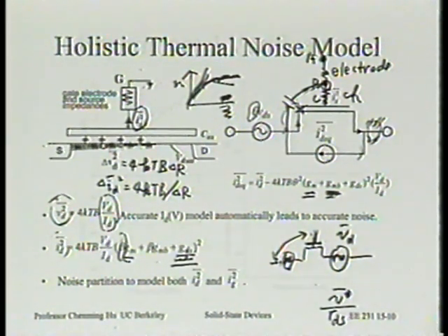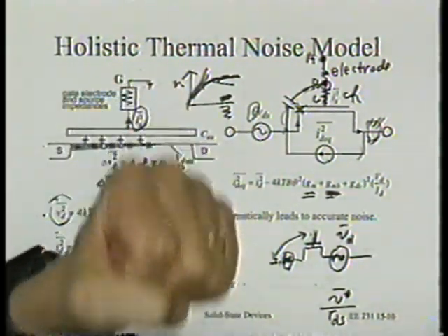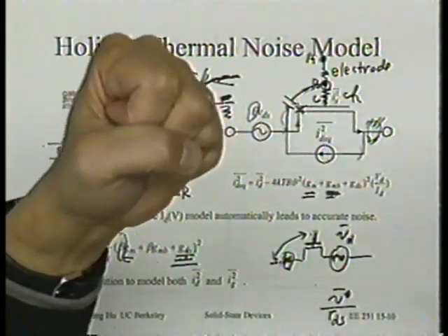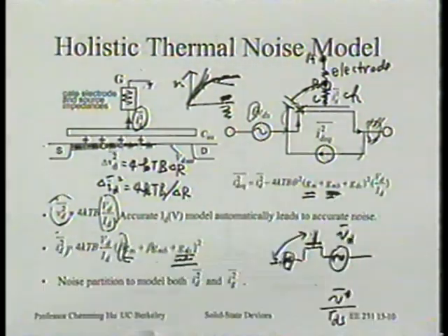The same thing as, this is a surprising thing to people sometimes, but it's a fact. Let's say you have two signal sources, let's say antennas, all right? One will produce an electric field of 1 unit, another produces an electric field of 1 unit, right? If they are coherent, they're going to add together, and the electric field becomes 2 units. Power will be 4, because power is proportional to the electric field to the second power, right?